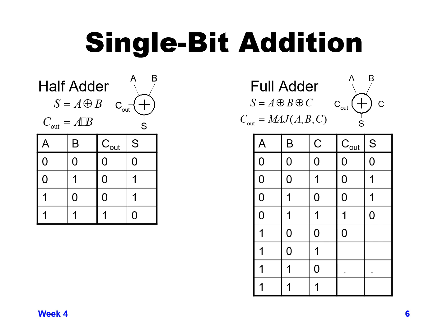The next one, since we only have one 1, we get the same result as no carry out, but our sum is 1. And then the following row, again, we have two 1s, so we should get a carry out, but since there's only two, our sum will only be a 0. And then the same is true of the next row. We get a 1 and a 0. And then finally in the last row, our majority of 1s, so we get a carry out.